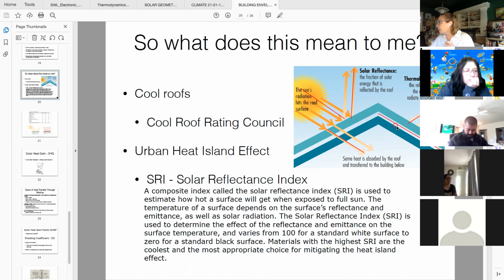Otherwise the radiation is going to hit that barrier, and if it's directly attached to its surface, that energy is just going to go straight through via conductance if you don't have a small gap. And the industry standard is about an inch. It doesn't have to be very big, but if you can't get that air gap in there, there's no point in putting it in.